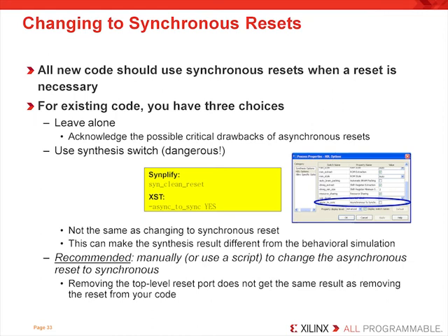However, the synthesis tools will put a register on a DSP slice or block RAM if it needs to be synchronous, but does not give the distinct optimization capabilities if the register was coded in the block RAM. So this option is not always complete, and do not expect this to be the same as changing your HDL. Keep in mind that if you don't code for a synchronous reset, in the future, another designer that works on your project will not know that you actually built with a synchronous reset. So keep in mind you may need to create a documentation trail.